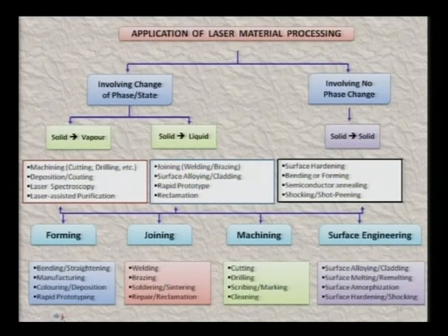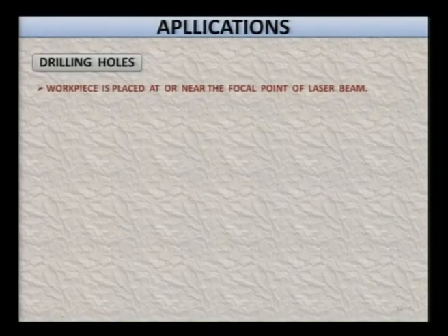So, I will give you some of the very important and interesting examples of laser macro machining as well as micro machining. I am not going to cover other applications like welding, brazing, etc. I will concentrate in this lecture only on machining, which includes macro machining as well as micro machining. Now, drilling of holes using laser beams, the workpiece is placed at or very near the focal point of the laser beam, so that the maximum utilization of the heat energy available due to the laser beam is made.